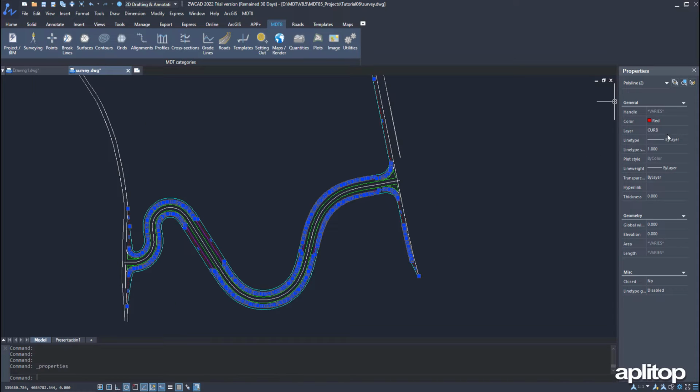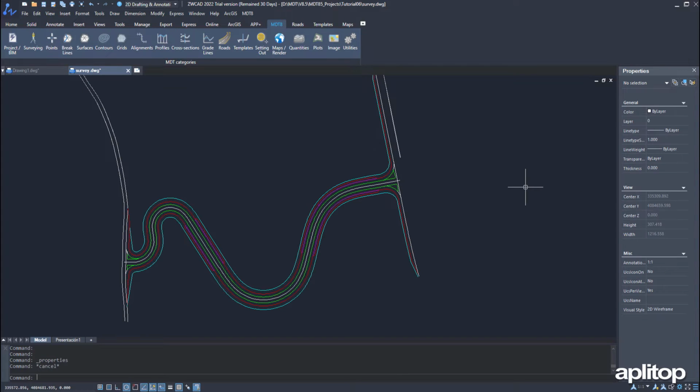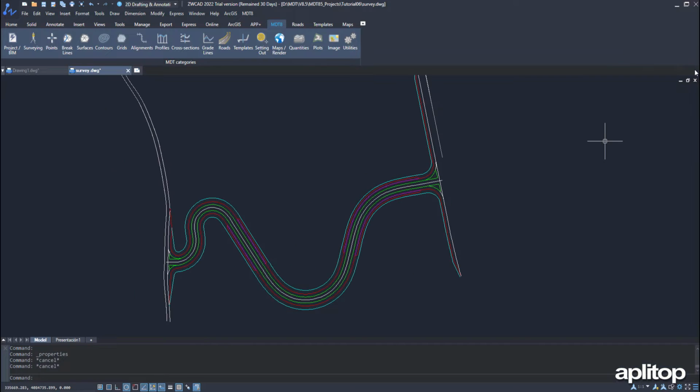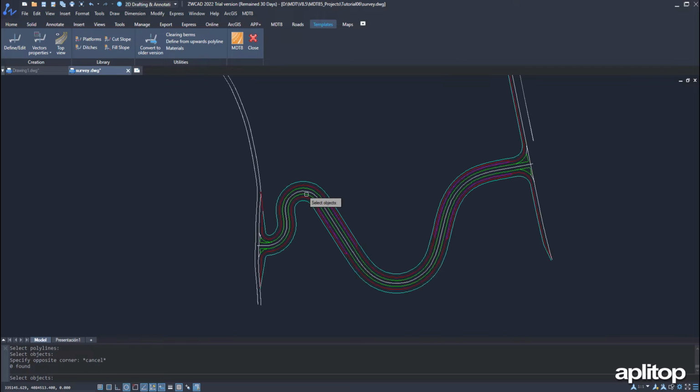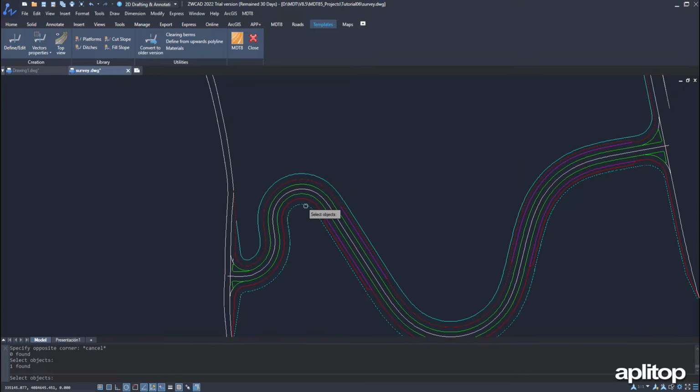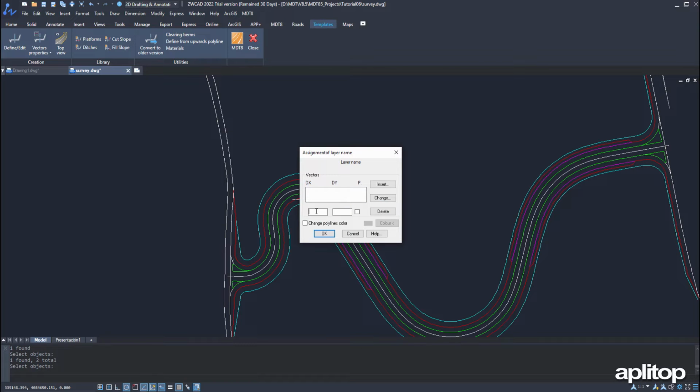To these polylines we are going to assign two different behaviors. The line of the curb foot, with the same elevation with respect to the polyline that precedes it, and the one corresponding to the top of the curb, which has a slope of 20 centimeters with respect to the bottom of the curb. To carry out this definition, we execute the command assign properties to platform vectors and select the two polylines that are in the curb layer, in red.